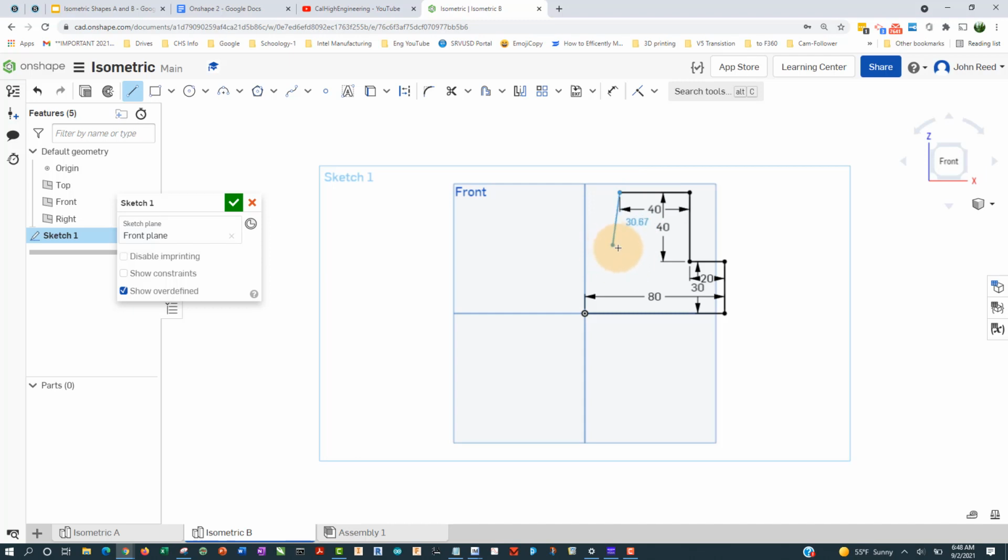And you see how I can move the mouse around and it'll snap to vertical? And I've got that little vertical line to the lower right of my cursor there, which says that I'm vertical. I can come down here and it'll catch up with the... Oh, no, it doesn't. Maybe if I come over there, you see how I can move the cursor over to this line and then gently move it over, and it'll make it the same length. So I don't have to put a 40 in there. So I'll click there and then click back over here. There we go. And I'm drawing it out.